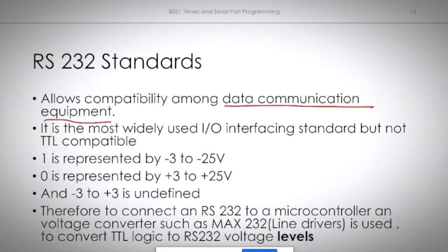Since TTL and CMOS logics are widely used now, to make them compatible with RS232 logic we will be using something called line converters.